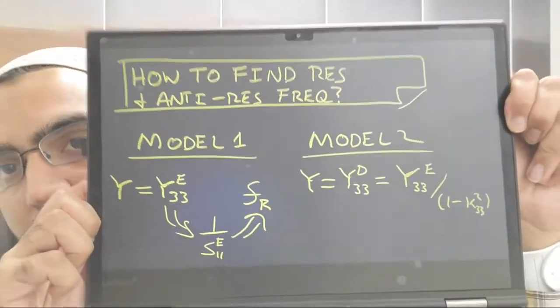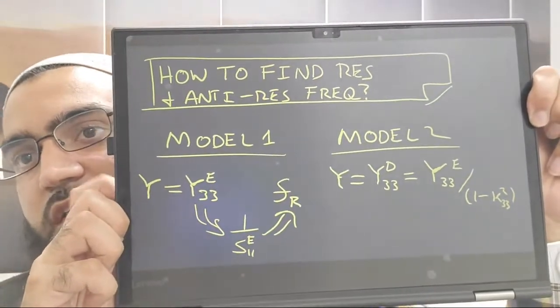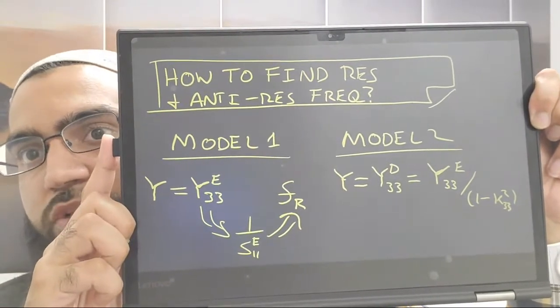Let's continue. So then you construct a new model, and you have new material properties. In this case, it becomes more useful to model your piezo as an isotropic material. Modeling your piezo as isotropic is fundamentally not true, but it can be useful. Like the saying goes, all models are false, but some are useful. This is useful. If you model your piezo as isotropic, because right now we're focusing on efficiency of the model, we're focusing on modal analysis, so you get results today, not several weeks from now.